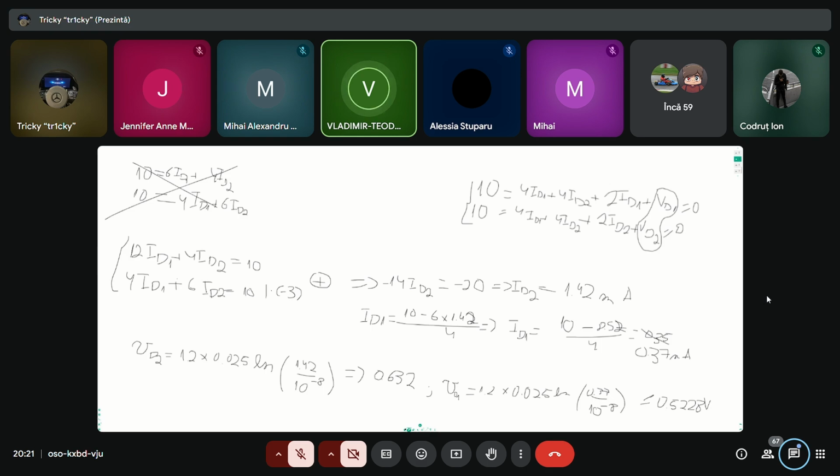And then after you get to the currents, you need to put them in the table and then redo the calculation with those currents to get new voltages and do this over and over again until you get basically the same precision up to 2 decimal points. You need to get a similar solution to the previous calculations, and that's the real value. That's the final value. Sorry, did you say you call those tables? I didn't understand what you said.